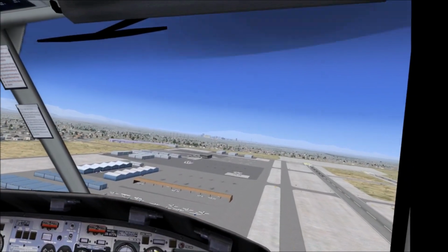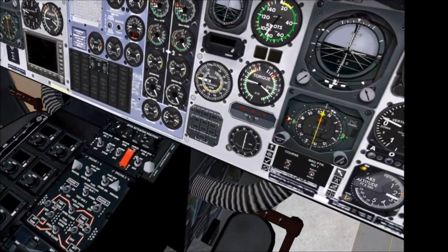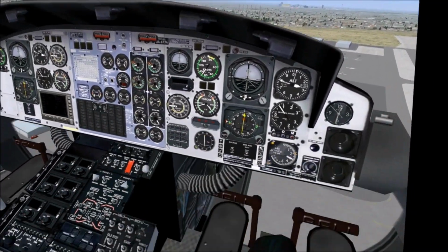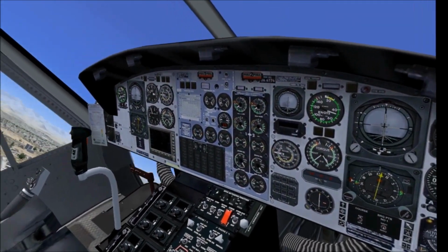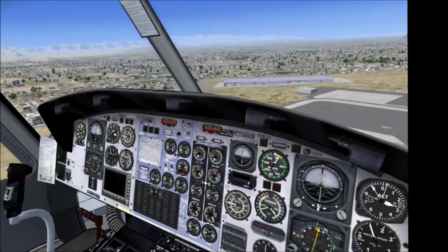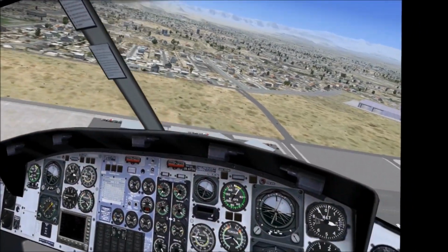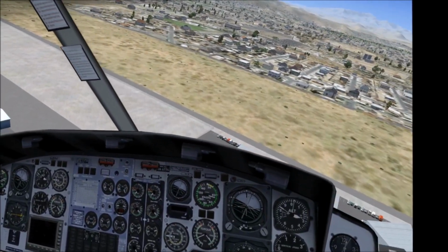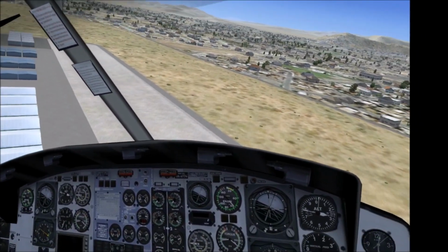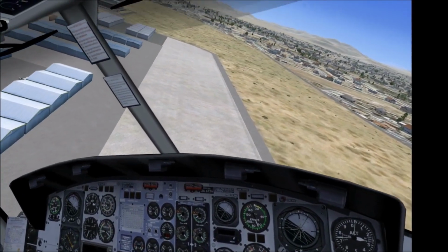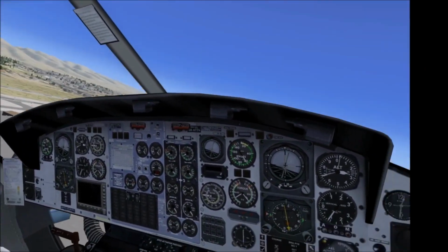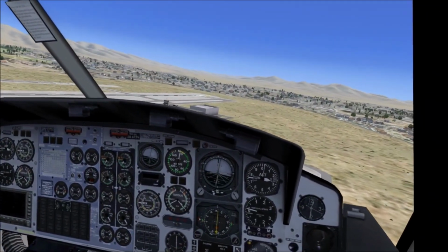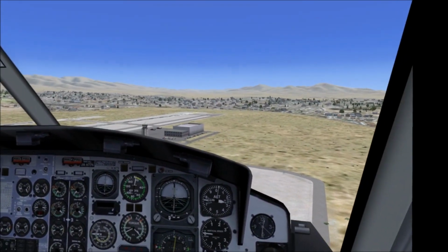So I'm just going to see if there's anything I can do to get that triple tack to fluctuate as far as manipulating flight controls. Because the quick stop didn't really do much. So collective all the way down, cyclic all the way back, nothing. I mean, short of rolling the throttle off, I don't think that I can get any sort of RPM fluctuation with the cyclic. That was a pretty rapid cyclic application with a pretty good amount of airspeed. I couldn't get anything out of it.